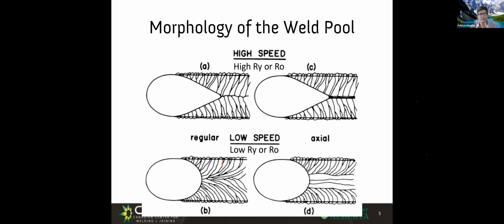This is powerful. And all this traces back to, if you ever want to do things quantitative, we're not doing it here. But for solidification, there are lots of formulas that tell you dendrite arm spacing, that tell you growth velocity, many things. And all those require parameters such as cooling rate. Typically, people who do solidification don't know all the heat transfer, but you know all the heat transfer now.